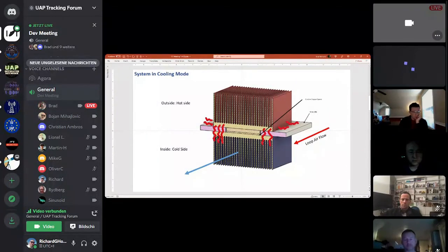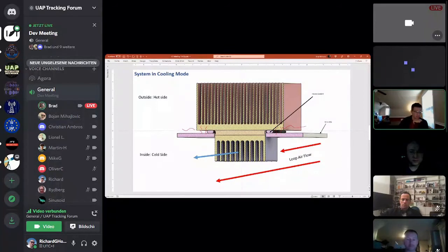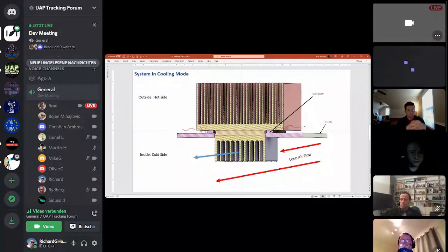So if you were to go to a smaller heat sink and seal it off and try to limit conduction as much as possible, you can get a little bit better efficiency. But the problem here is the footprint of this is only about 40 by 40 millimeters, and maybe you can get them 30 millimeters high. What's the cross-section area of our duct, Richard? 8,000 square millimeters. But so we wouldn't be covering the entire interior of the duct. Yeah, I get the point.